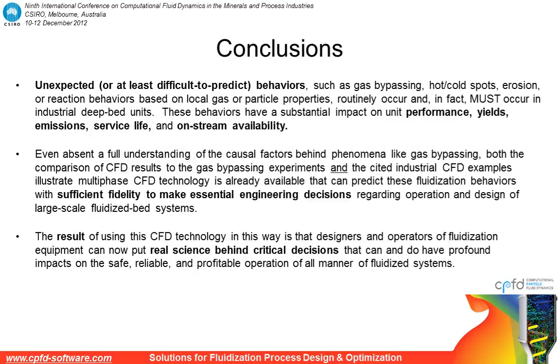In conclusion, unexpected, or at the very least difficult to predict behaviors such as gas bypassing, hot or cold spots, erosion, etc., routinely do occur and in many cases must occur in industrial deep bed units. These behaviors have a substantial impact on unit performance, yields, emissions, service life, and on-stream availability.